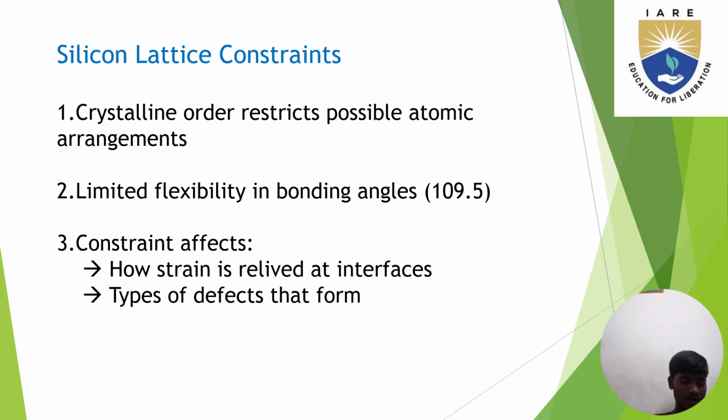The states are localized at the interface between a semiconductor, for example silicon, and another material, for example an insulator or metal, because they can trap, emit, and recombine charge carriers, electrons and holes. Interface states degrade the performance of semiconductor devices like MOSFETs by causing instabilities in the threshold voltage and reducing